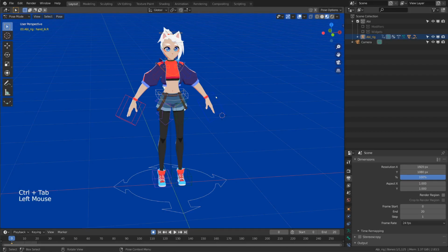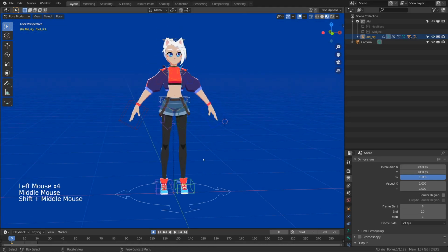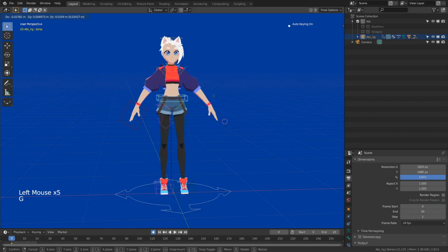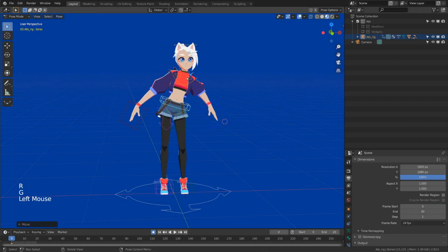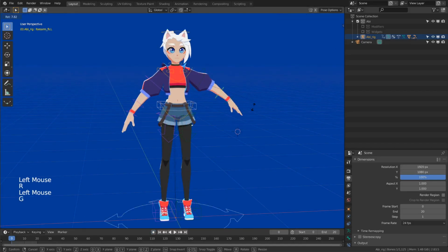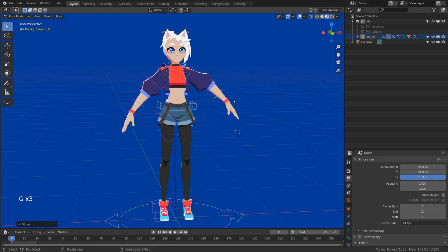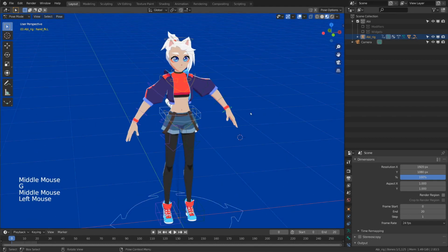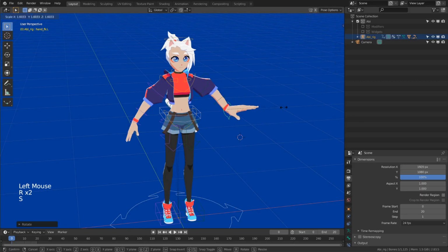This will change the color of our armature to begin representing the individual colors of each bone. Typically bones will be blue by default, but some rigs have custom colors to make it easier for the animators to identify. Once we have the armature in pose mode, we can select each bone individually and begin transforming them freely as we would if they were an object. Keep in mind that some bones may be connected to their parent bones, and thus cannot be translated but only rotated. But other than that, it should work exactly the same as other transformations in Blender.